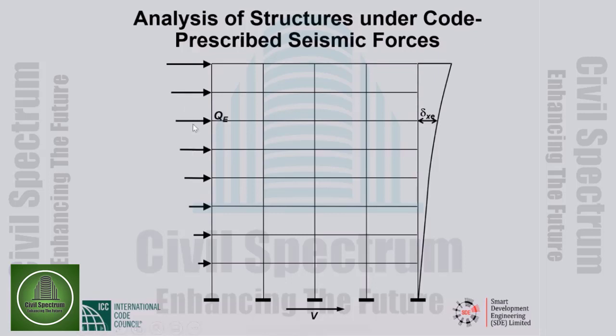That analysis gives us two very important things. It gives us bending moments, shear forces, axial forces at various critical sections of various structural members, the generic notation for which is capital Q sub capital E. Q sub E is bending moment at a beam section. It is shear force at a column section. It is axial force in a column. It is generic notation for all internal forces.